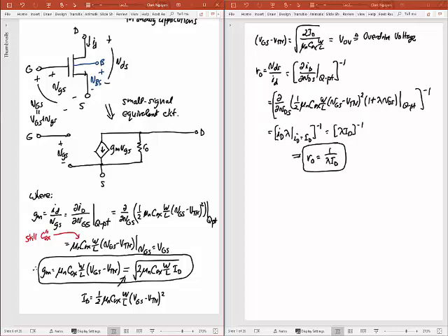And so I'm writing that as a large signal bulk signal here, but this actually is equal to, right, the DC term plus the small signal VBS. And what is this doing? When I change VBS, what does that do to an MOS transistor? It changes the threshold voltage, right. And so if my threshold voltage changes, but my gate to source voltage doesn't, that's still going to cause a change in my current ID. Okay? Which means I have to model that now with my small signal circuit.